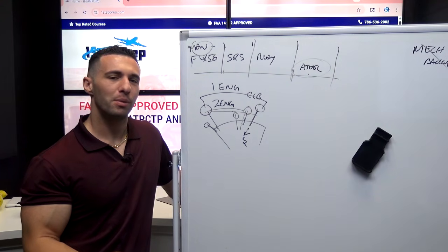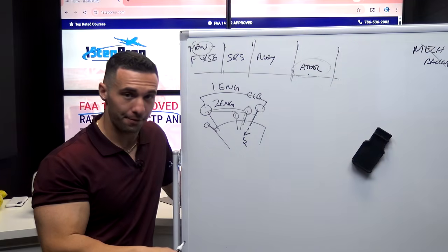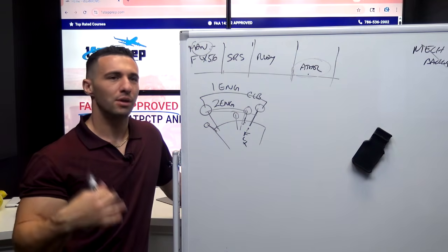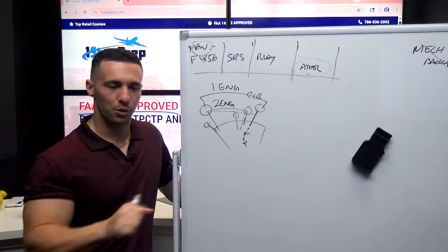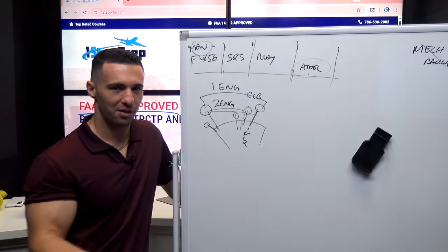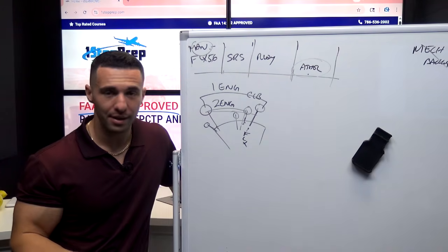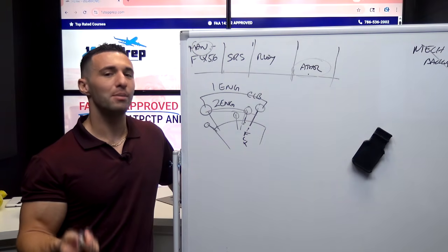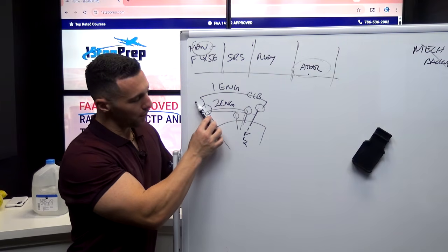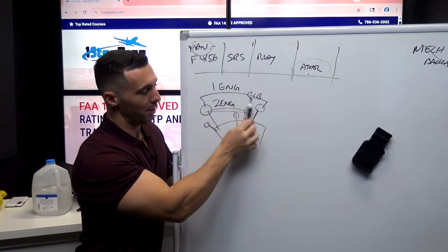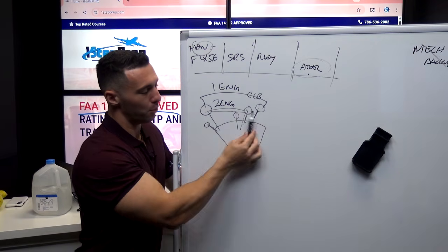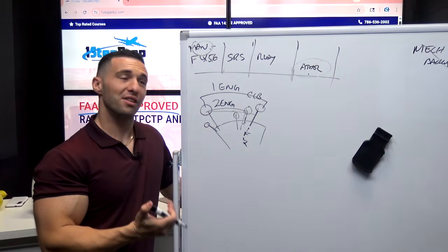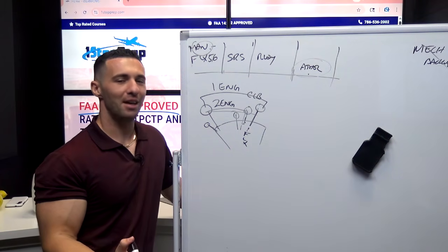So that's why I like to tell people, if the auto thrust is off, your thrust levers are thrust levers in all the traditional context of what you would expect a thrust lever to do. Reduce, it reduces, add, and it increases thrust. If auto thrust is on, then the thrust levers are not levers, they're limiters. They are now thrust limiters, meaning wherever the thrust lever or limiter is placed, that's going to be the limit of how much the auto thrust has the range or the authority to give you thrust, which it doesn't like to be limited, which is why it'll spit an ECAM if you do end up limiting it at all.